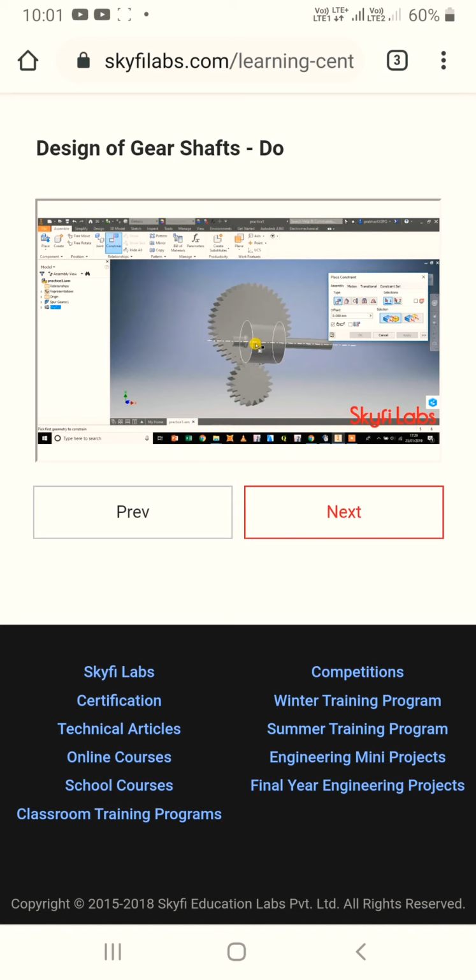We can set different assembly constraints: make two parts coincide, align multiple parts at a preset angle with each other, set two parts tangential to each other, insert one part into another, and make multiple parts symmetric to each other about a plane or an axis.